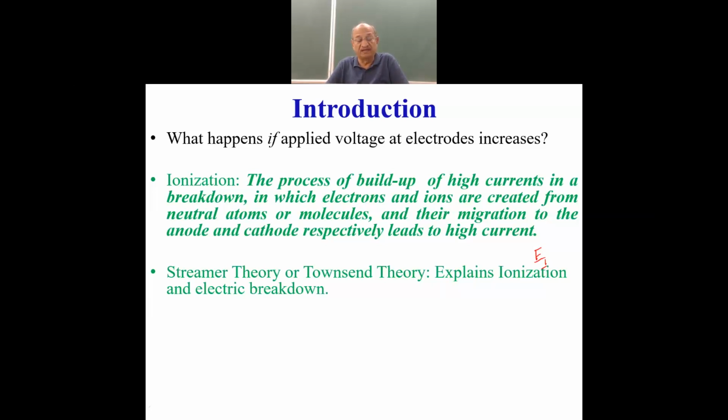That is, an avalanche contains both electrons and ions. When you increase the voltage further, the avalanches acquire a certain size. We put it as critical amplification of avalanche. And when critical amplification of avalanche is able to develop, we call it the streamer process begins.